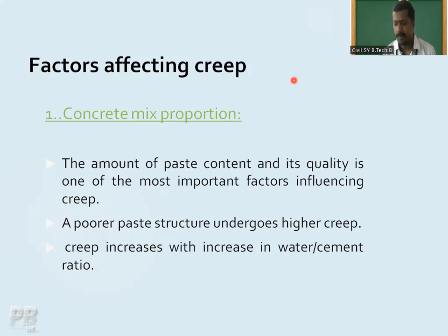Water to cement ratio, why is it important for us? In case of cement, why is consistency the most important thing? Because through that test only you will come to know the exact amount of water required to make a good cement paste. So likewise, during the discussion, we will have some discussion about such questions also. I'm happy that somebody has responded in the chat box correctly.